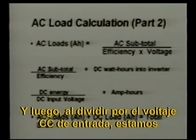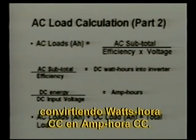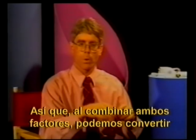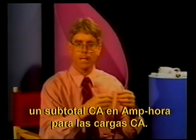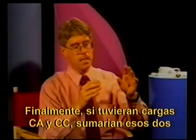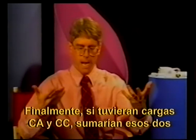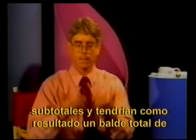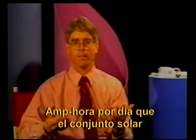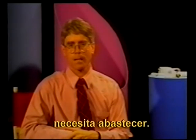And then by dividing by the DC input voltage, we're converting DC watt hours into DC amp hours. So by combining these two factors together, we can convert from an AC subtotal into amp hours for our AC loads. Now, finally, if you had AC loads and DC loads, you would add those two subtotals together to get a total bucket of amp hours per day that the solar array needs to supply.